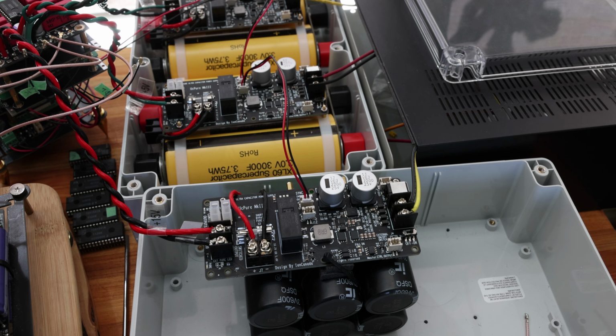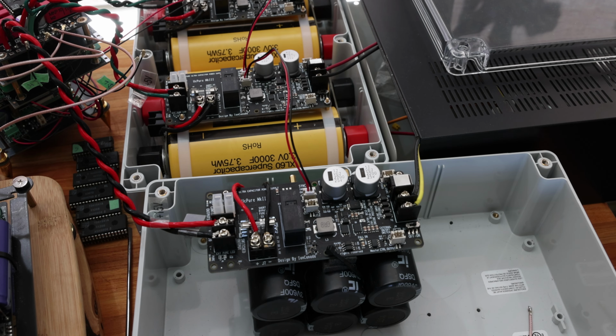Make sure that your capacitors have at least up to 4.5 volts before you power your system, and you're at least above 12 or 13 volts on the 15 volt side. Anything lower than that, your TDA is not going to function well, it's going to create this buzzing noise, and you're going to be wondering what the heck is going on. So if you hear that, that would be the culprit.